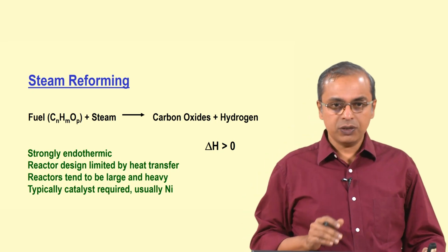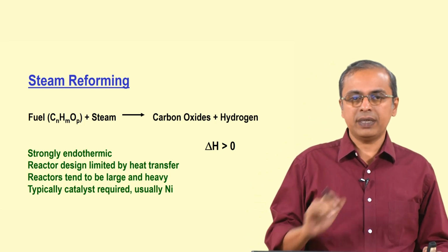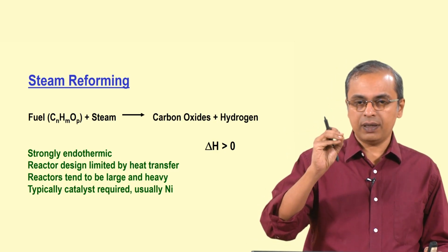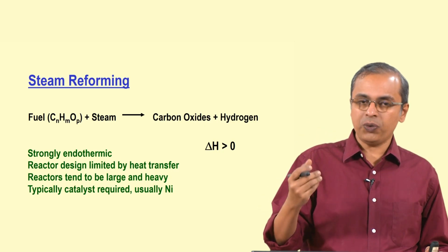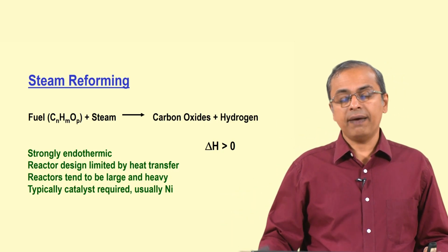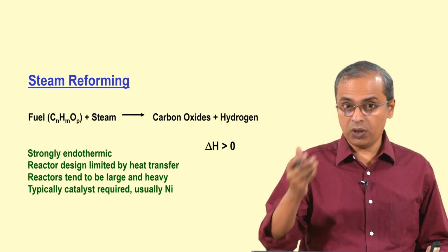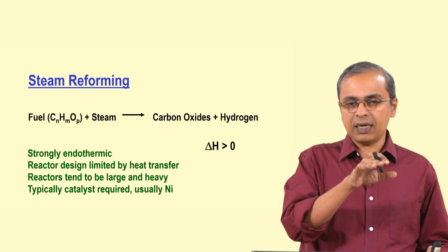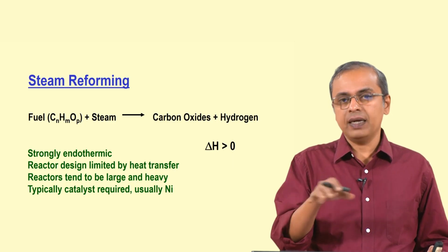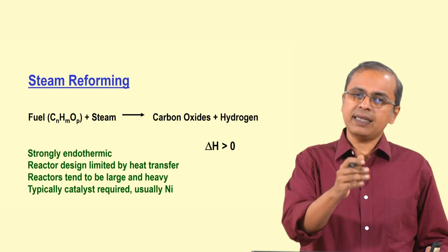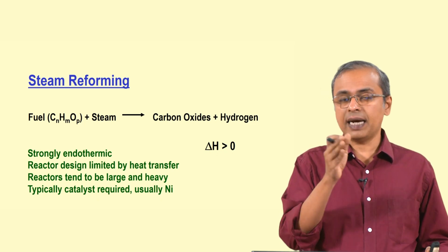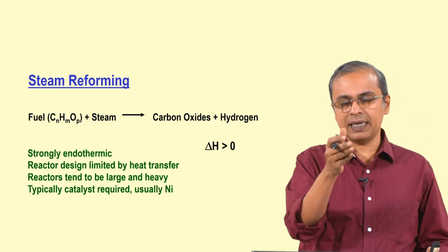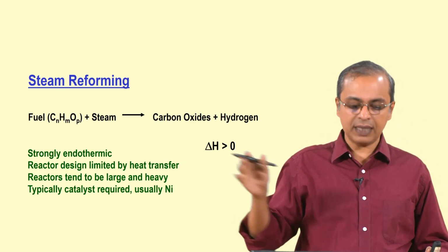So, what is fuel processing? The basic idea, at least with respect to the fuel cell, is that you want the inlet of the fuel cell to receive a stream of fuel that is rich in hydrogen. Okay. As opposed to the lab setting where you are testing just pure hydrogen, you now want a situation where the inlet is some processed fuel, and the output of that processing step is a fuel stream that has a lot of hydrogen in it, and therefore, the fuel cell can work with that hydrogen. The hydrogen may not have been inherently present as a separate entity in the original fuel. You process it to separate the hydrogen out, and then you send that hydrogen into the fuel cell. So, that is the basic idea.